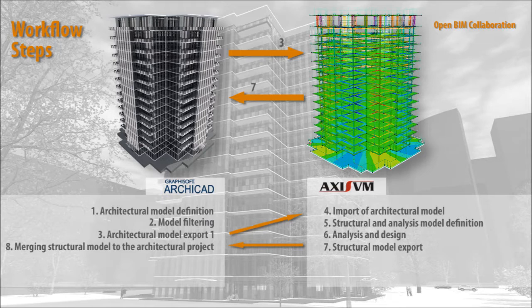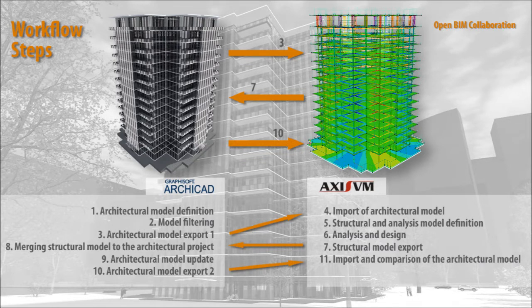Architects may compare two view sets, one of the architectural model and the other of the imported structural model. Architects can query the profiles and materials used by the engineers and modify their project to match the imported reference model, or they can accept imported elements by using them as real ArchiCAD type elements. After review, architects can then export a new IFC file based upon the project's new status as a revised model. The engineer then opens the new architectural model and compares it with the previous architectural model version.